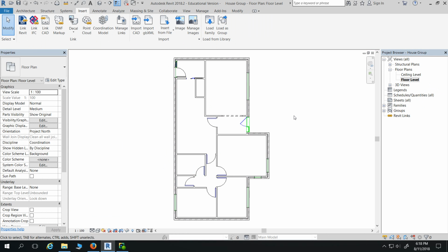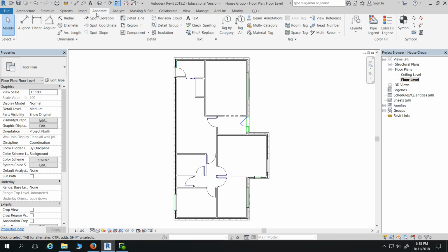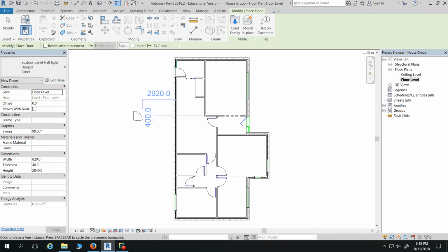above the CAD. So what I was going to do for you guys while you go through putting the windows in is I'll create a schedule which you guys can use to put in yours. Bit of a forward thinking thing as well. When I'm putting a door or window in, I turn tag on and placement off, because it's a bit annoying.